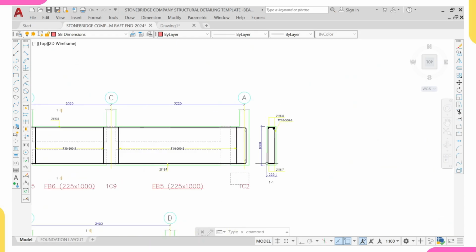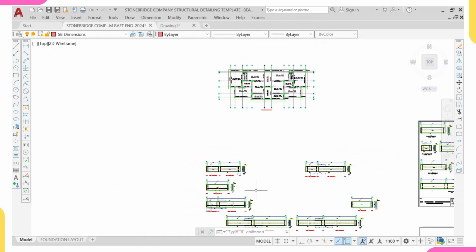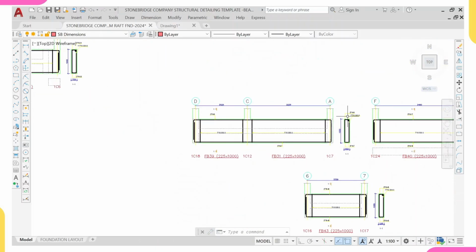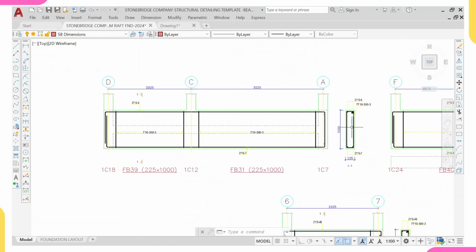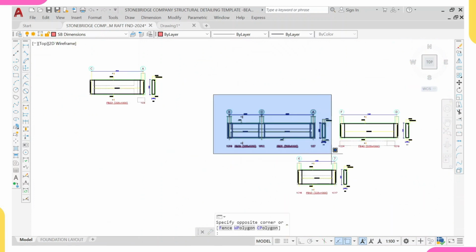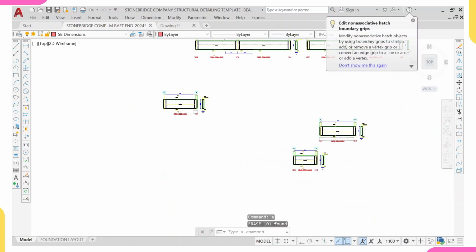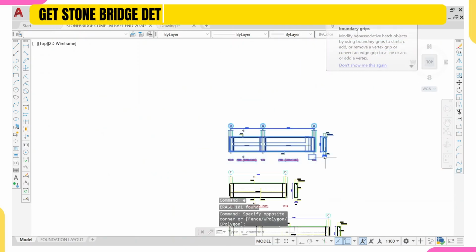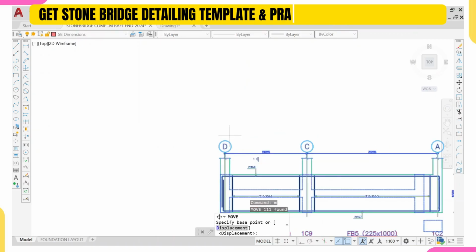If you can see, it's 2y16, 2y16, 6. This one is 6. Then let's check for 39, because both of them are the same thing. So this is 39. If you see, both of them are exactly the same, 2y16, 2y16. Remember what I said about the web bar. So I'll delete this, I'll do E, enter, and then copy the one of 6. I just deleted only one and copy the other one because they are typical. I'll do M, enter. M stands for move.